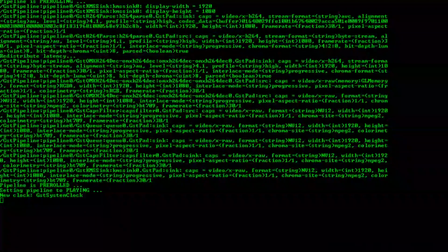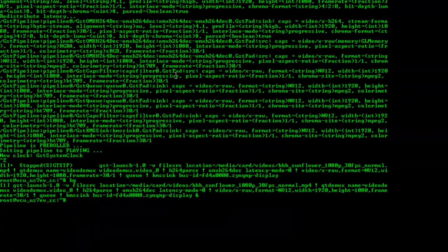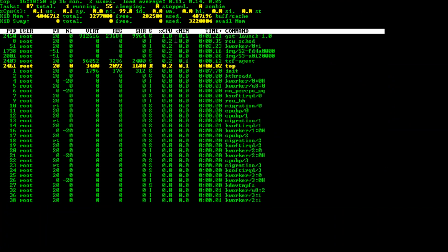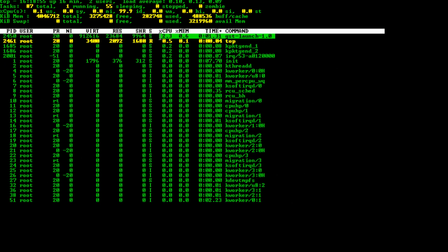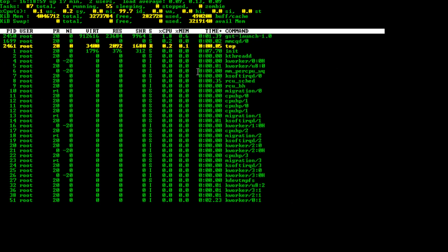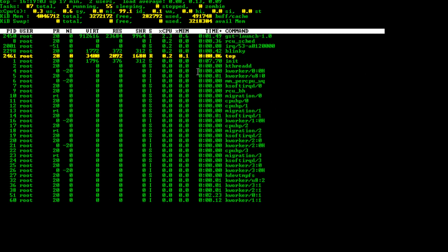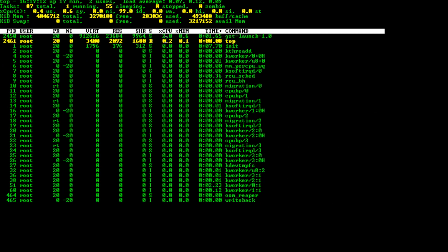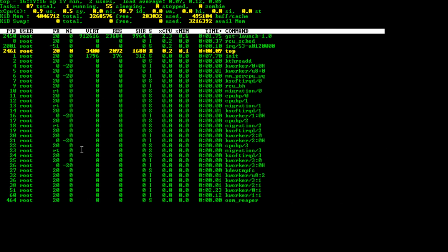Now I'm going to hop back to Tera Term for a moment, and we're going to put this in the background and take a look at what the processor is doing while this video decode is going on. Let's let this refresh a time or two. I want you to look at the top of this list. You'll see that gst-launch is taking a little over 2% of one CPU core. If you remember, in our 720p video test pattern the processor was generating, that took 27%. When we bumped that up to 1080p, that took 60-plus percent. Now that we're doing a hardware video decode of 1080p 30, the processor is only involved 2% of the time for one core.